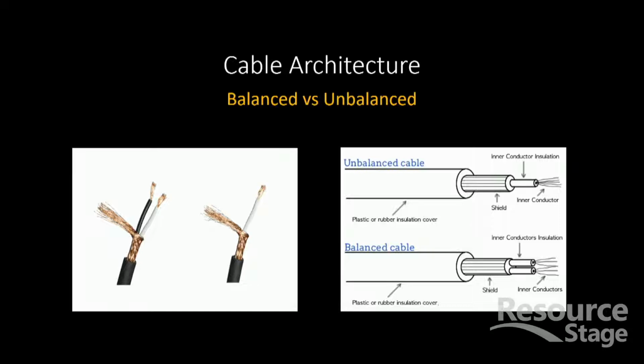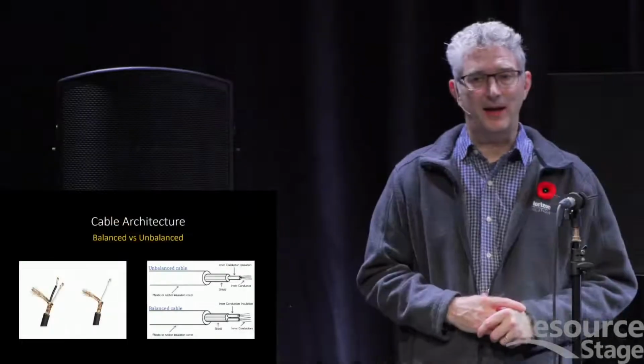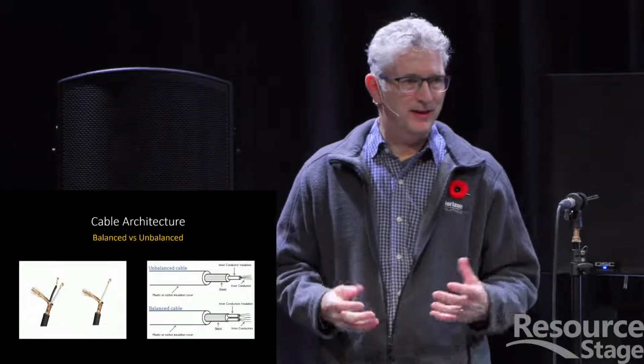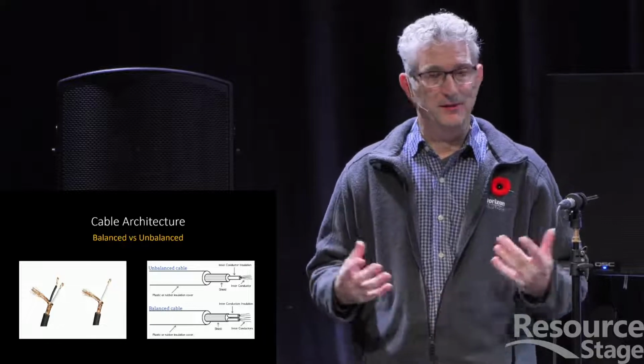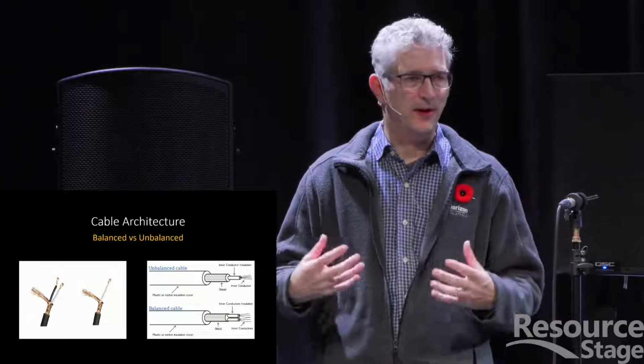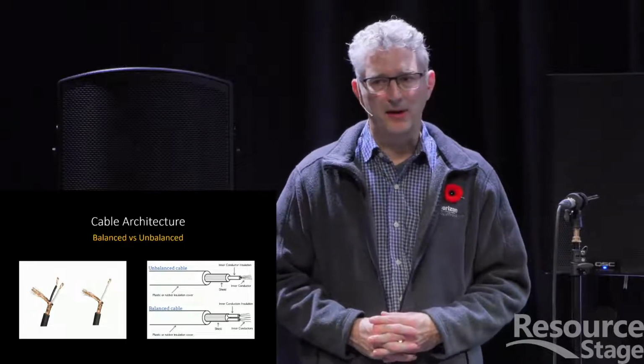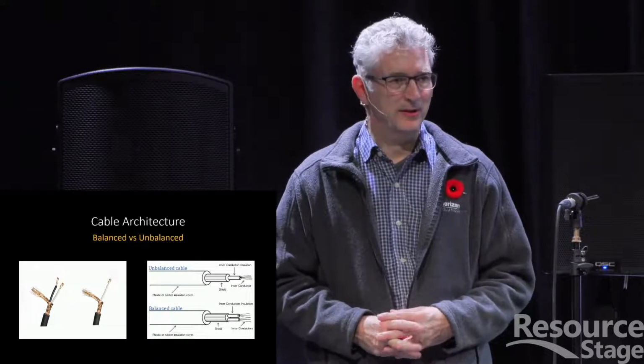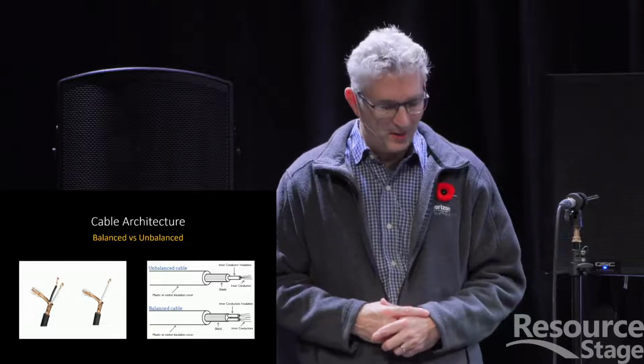So the maximum distance of an unbalanced cable is recommended to be only about 25 feet, because anything longer than that, you're very susceptible to picking up some interference and causing noise in the audio path.